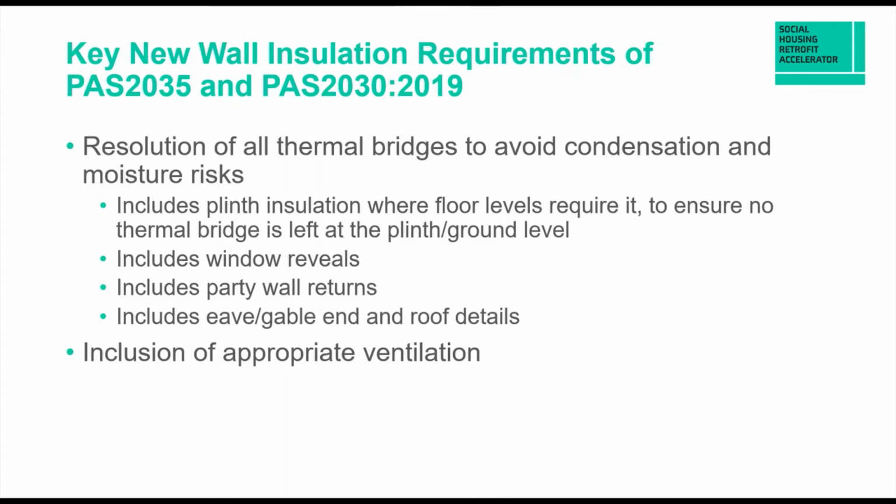So thermal bridge calculations are quite important. So you need to take into account the fact that those sometimes take time to do. And they also need to be specific to the construction that you're working on. So sometimes system designers, system providers will have standard details and they will have standard psi value calculations and standard temperature factors. But if your underlying construction on your building is not the same as that standard detail, those numbers don't mean a thing. So you have to make sure that that actually does line up.